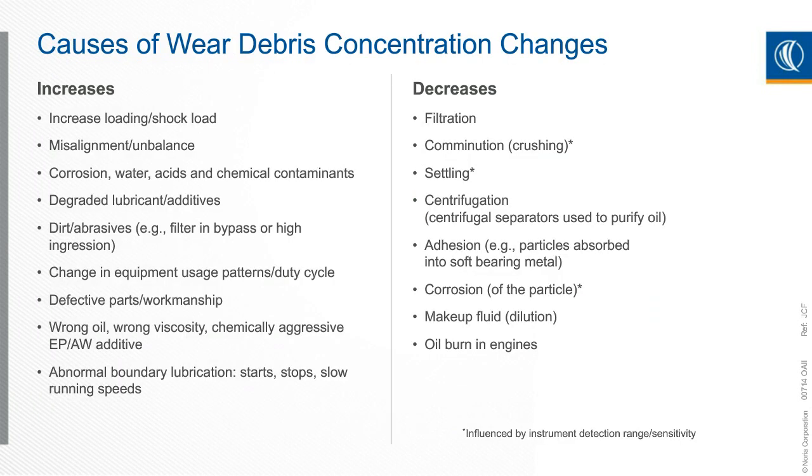As you look at the third category of oil analysis, wear debris, we need to know what causes changes in wear debris concentration. So an increase would obviously mean something is happening in the machine. It could be an increased loading. It could be a misalignment. There could be corrosion occurring. That's when you need to take action to do exception testing to figure out what might be going on inside your machine. A decrease in wear debris, well, that could be maybe filtration.